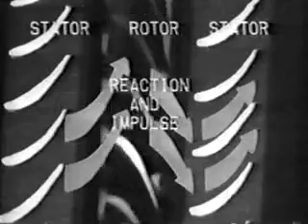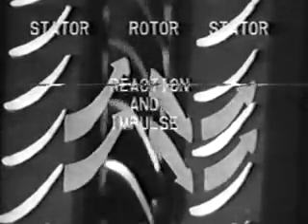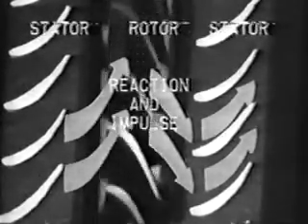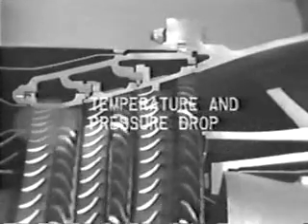turbine shaft. The Centaur turbine uses air in both ways, impulse and reaction. An impulse of air striking the leading edge of the rotor blade, and expanding air reacting against the blade's trailing edge. Both ways together maintain the evenness of the turbine's rotation at operating speeds. The expanding gases drop in temperature and pressure.